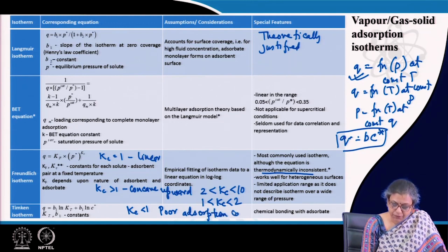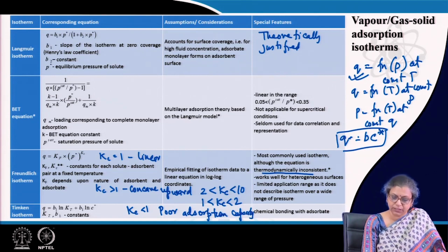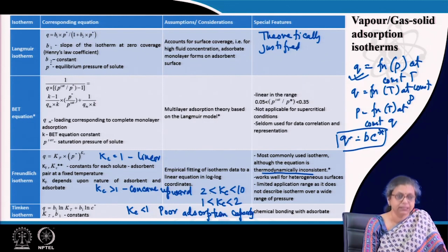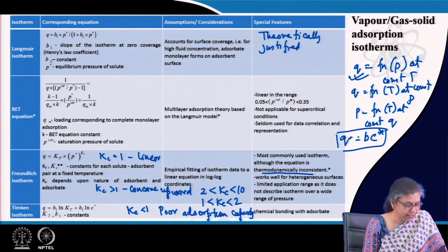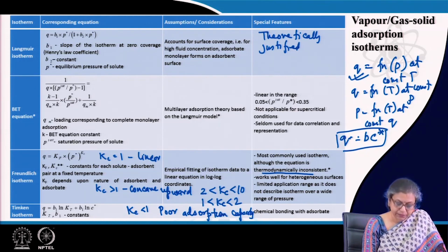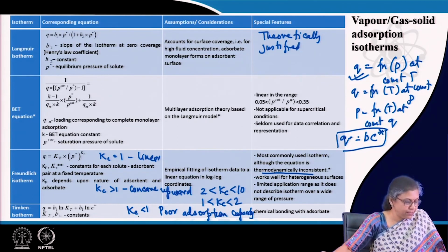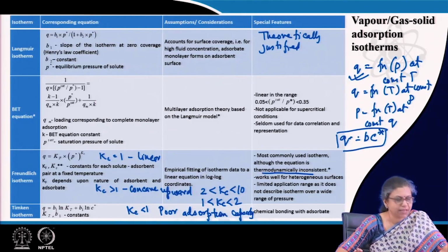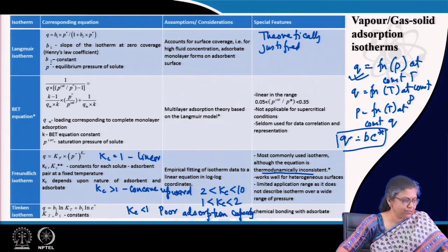So if we would like to select an adsorbent, we would like to ensure that the Kc value is greater than 2. In that case the adsorption is going to be effective. And we definitely do not select any adsorbent which yields a Kc less than 1. Well, with these things said, we have discussed adsorption. The next topic is liquid extraction.